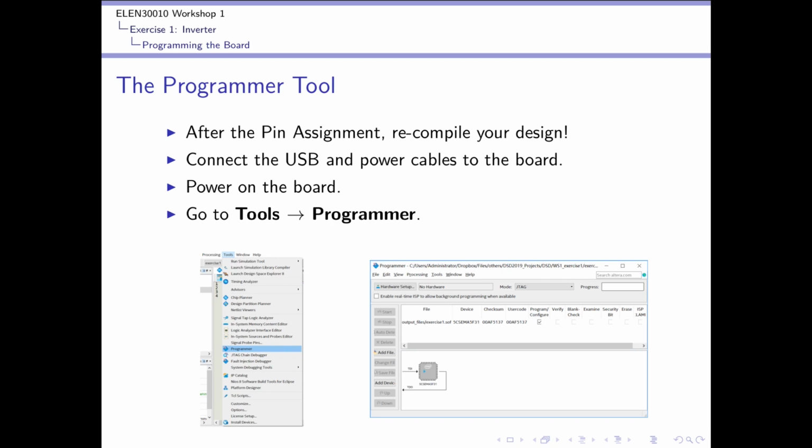So I want to emphasize, and I'll do this a million times throughout the course, the FPGA is not a CPU. We are not programming it. We are configuring it. Once it's configured, it's just like an ordinary digital circuit that you soldered together by hand. It's not executing any code whatsoever.